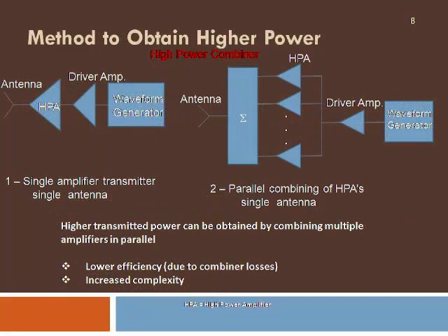So here we will see how this high power amplifier can be introduced into the radar system. If we are going to have separate antennas like in a phased array system, we can use separate amplifiers for each of the antennas as shown in the first diagram. So here every amplifier will be separately fed with the DC supply and the signal input, and the output of this amplifier will be directly connected to the antenna.